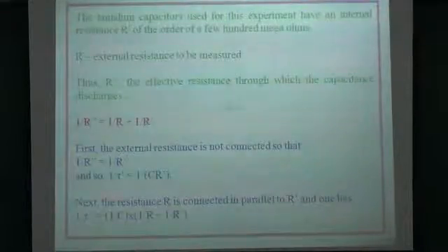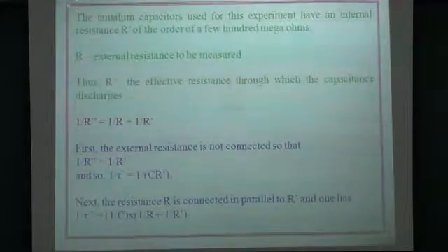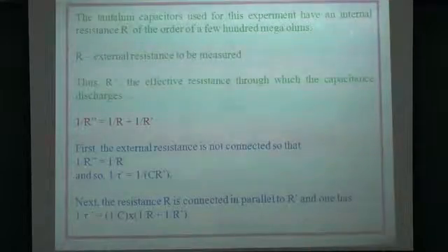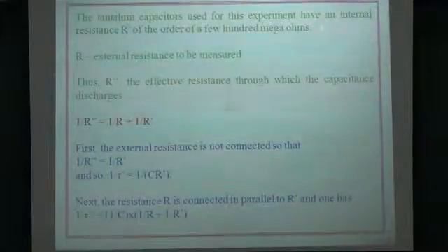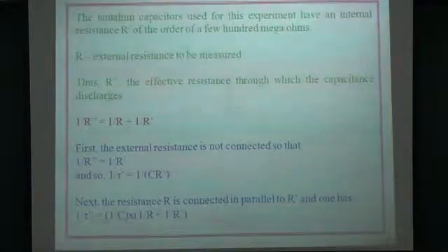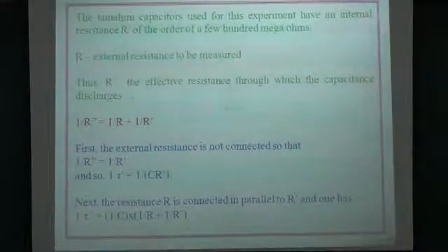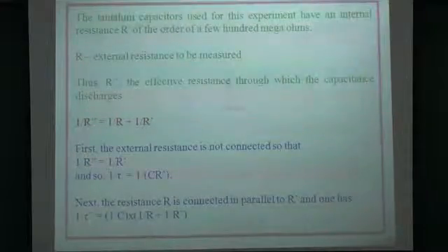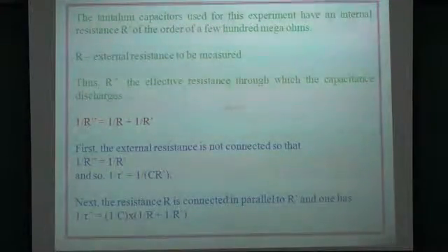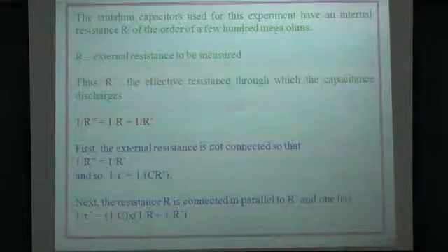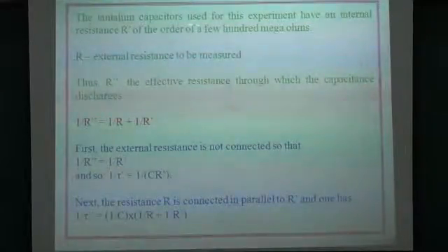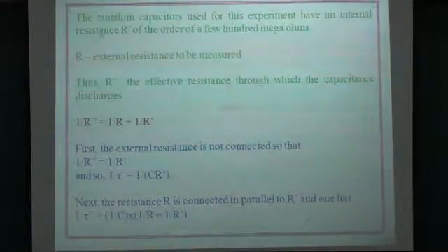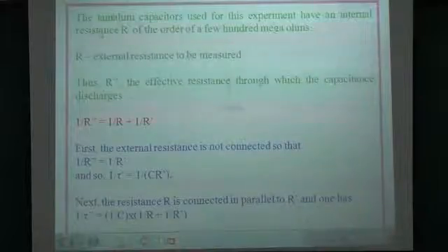But what we do here is, we are making use of a polypropylene capacitor in this experiment, which has an internal resistance of the order of a few hundred mega ohm. That means you charge the capacitor and you leave it to discharge. So it will discharge because of its own high resistance. So we will first allow the capacitor to discharge because of its own resistance, and then